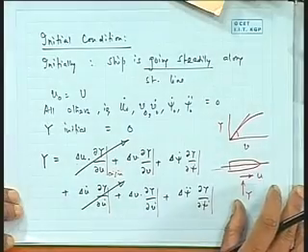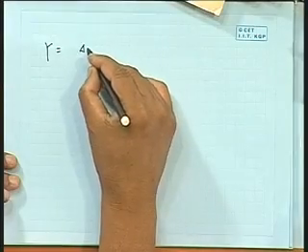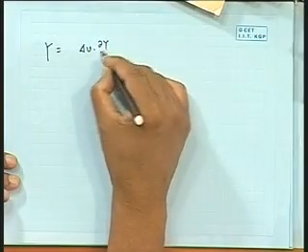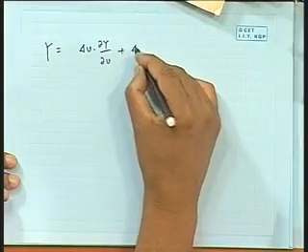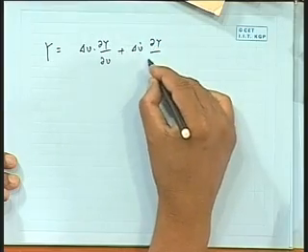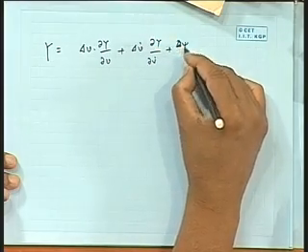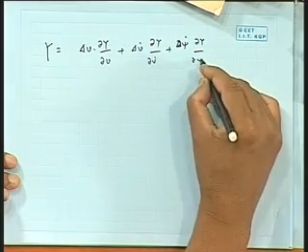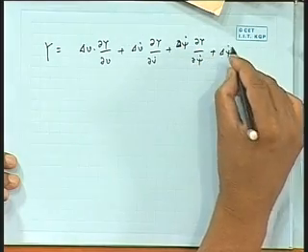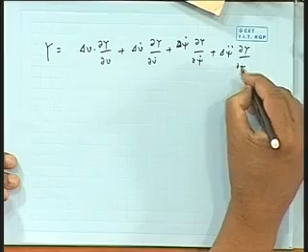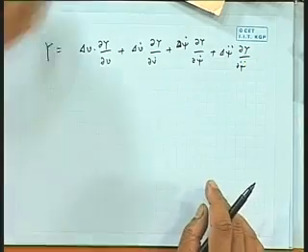This is a very important and interesting part of that. So, what I end up getting is that the y force becomes equal to delta v into dy by dv, plus delta v dot dy by dv dot, plus delta psi dot dy by d psi dot, plus delta psi double dot dy by d psi double dot. Okay, this is what we end up getting.